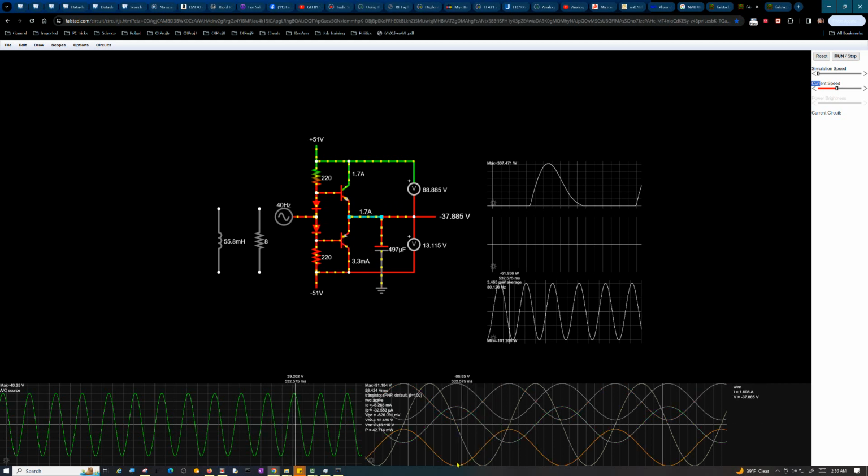But the same thing happens with this transistor. At the same time, it's fully off, but then over here, for example, it's fully on because it's as close to ground as it gets. So that's why I have this waveform on here in addition to these 2 meters. But you can kind of discern what's basically going on here. I mean, you've got current flowing. You can see where peak power occurs, but it's not at full voltage drop across the transistor.